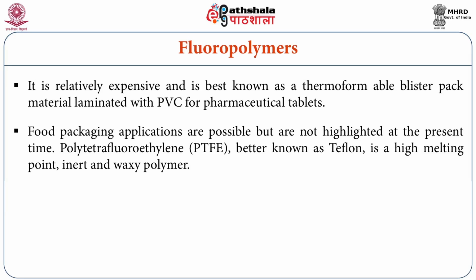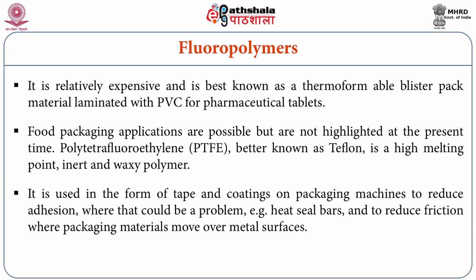Polytetrafluoroethylene, better known as Teflon, has a high melting point and is an inert and waxy polymer. It is used in the form of tape and coatings on packaging machines to reduce adhesion, where that could be a problem such as heat seal bars, and to reduce friction where packaging materials move over metal surfaces.